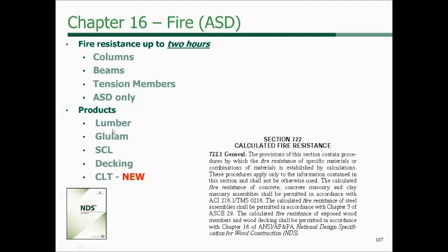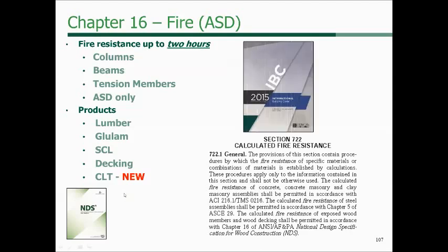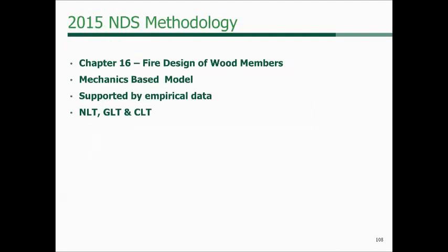Now, covered in this chapter is lumber, glue-laminated timbers, structural composite lumber, decking, and then new to the 2015 NDS is cross-laminated timber, and that's what the 2015 IBC references. And the methodology in Chapter 16 is based on a mechanics-based model and supported by empirical data, the testing data.